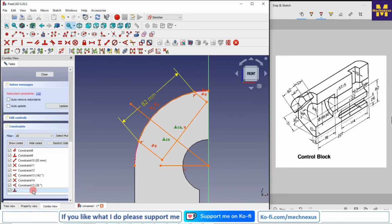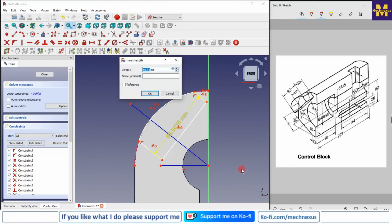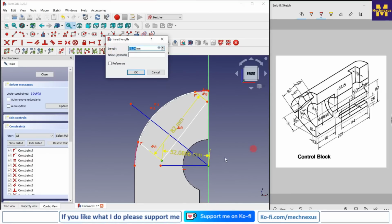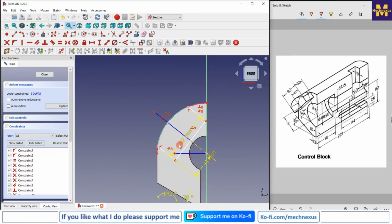So here is a conflict because we have already defined the perpendicularity with this. So now I will use symmetricity and I will select this point and this point, and this one. I think construction will not take, so I will delete this dimension. So I will select this line and I will give it 82, and from this point to this point, let's select this point and line, 41. So that is how it would be.